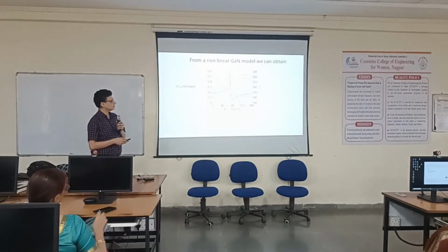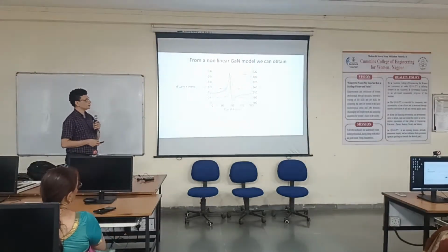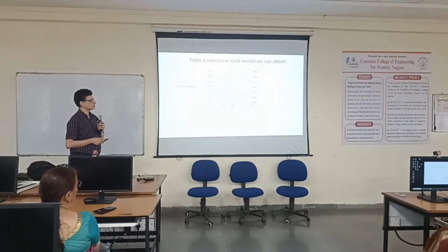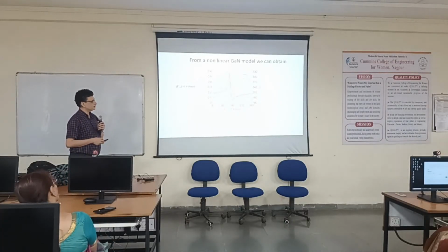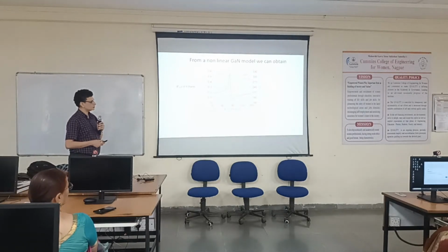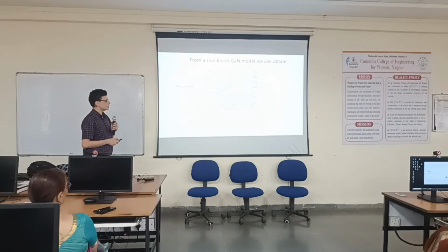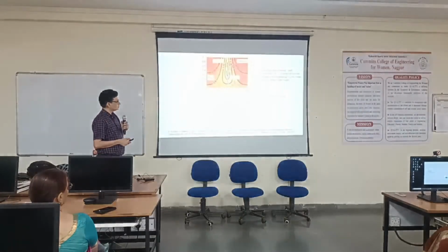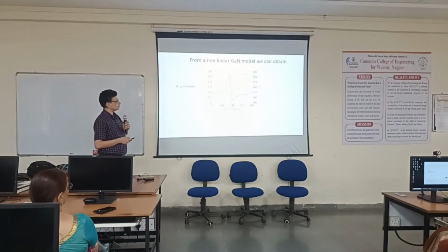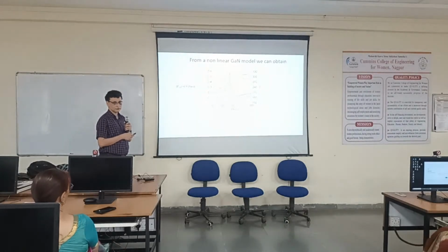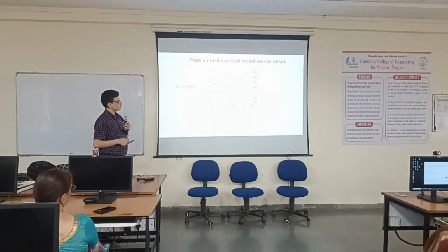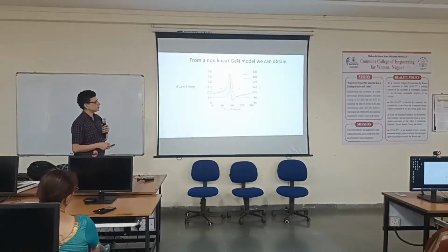So this is the device that we selected. This is a gallium nitride model transistor given by Cree. And this curve represents the nonlinearities. Gamma represents the amplitude nonlinearity, and phi 2 represents the phase nonlinearity. If we keep the second order harmonic reflection coefficient magnitude fixed at 0.9 and keep changing its phase, then these are the various values of gamma and phi that we obtain.